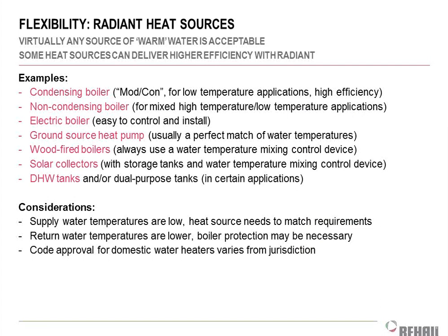So we use that ground loop as the source for the compressor-based system to then provide hot or chilled water to your house. Typically, we can't get 180-degree water out of a geo system. It's not really realistic without having a significantly oversized geofield. But we can get 110, 120, 130 degree water from our ground source heat pump system, and that is perfectly suitable for radiant floor systems.